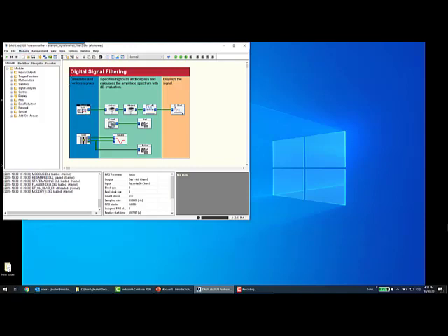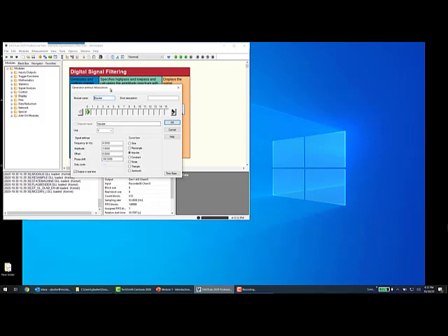You have modules, you have wires that connect the channels, the output channel of a module to the input channel of another module. Each module, when you're working with it, has a properties dialog, so that if I right-click over the module and go to module properties, it's going to open up a properties box that's specific to the type of function. This is a generator that's creating an impulse function at 4 hertz with an amplitude of 1.